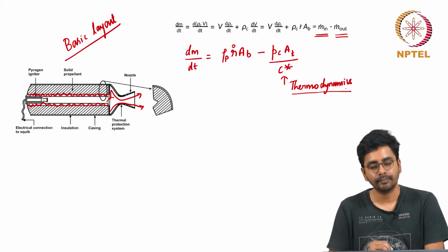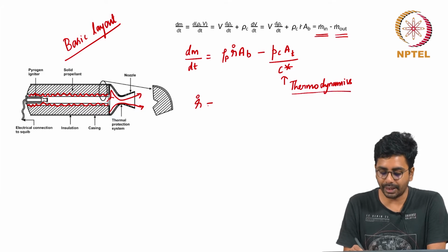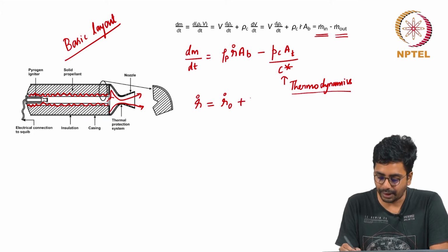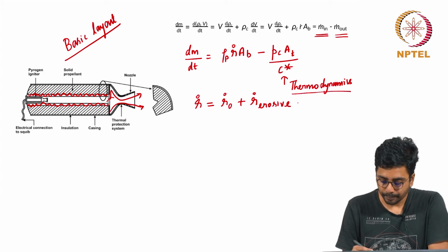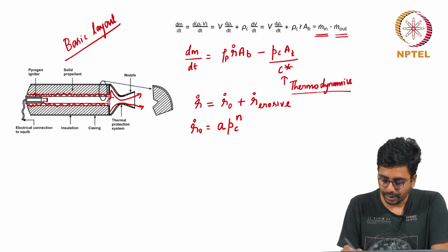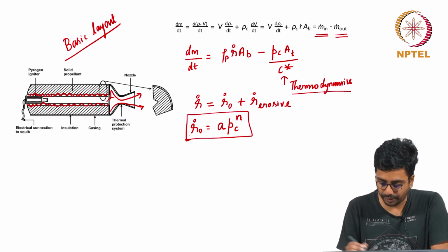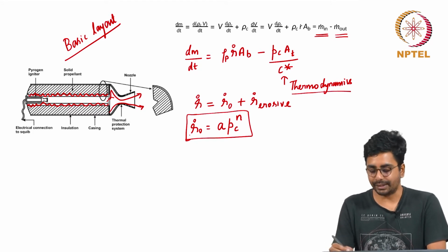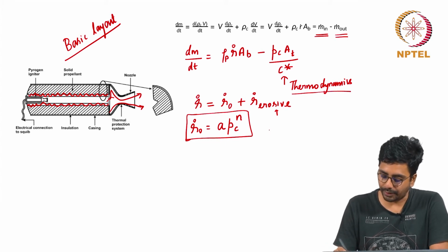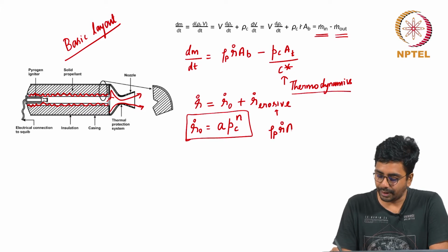And r dot, which is empirically determined usually, has two components. One is called the intrinsic burn rate of the propellant and the other is the erosive burning component. This r dot 0 is usually a power law function of pressure. In the simple case where, let us for a moment ignore the erosive burning component, the equilibrium pressure of a rocket will be simply governed by the balance of the incoming mass with the outgoing mass.